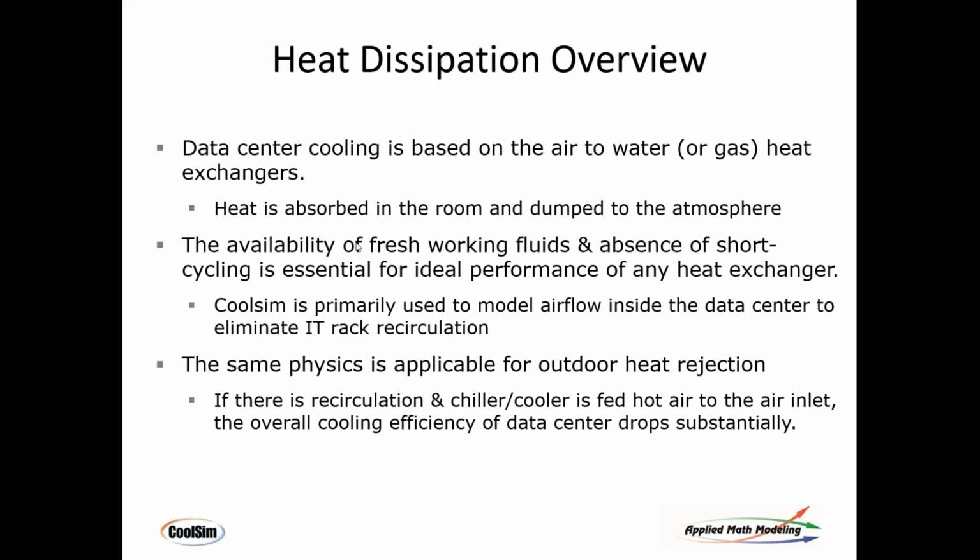Now, CoolSim is primarily focused on inside the data center and trying to dump the heat through the air handlers, or CRAHs or CRACs or Crays, whatever you want to call them, in the room. They're fundamentally heat exchangers. You're trying to get hot air back to them and you're trying to get cold air out of them.